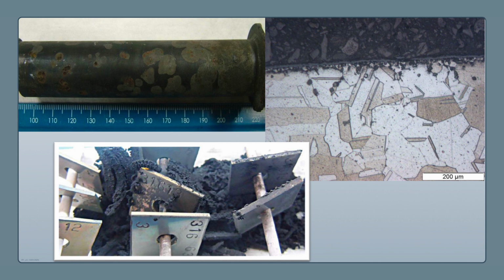On the picture on the right, we have a cross-section of this specific tube. It's called a ferrule, and I think it was austenitic stainless steel, if I look at the microstructure, where you can see on the surface this very thin layer. The top gray, which looks like cement, is the mounting resin. In between the mounting resin and the alloy, there's a thin layer, which is the carbon or graphite layer that forms. This is often referred to as a cement type of product.